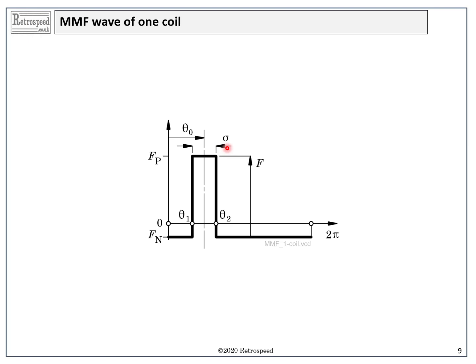But we ignore the even harmonics on the assumption that the winding is going to be balanced between its north and south poles. But we should take note of the fact that if this balance is not perfect, the winding will have even order MMF harmonics, and it will cause even order flux harmonics, and these will tend to flow in return paths which include the shaft and bearings, and which will be a source of trouble, including noise. Any oscillatory axial forces can cause the rotor to vibrate in the axial direction, which is not good for the bearings.